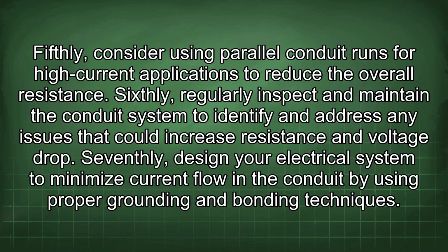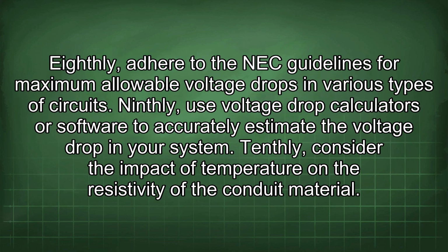drop. Seventhly, design your electrical system to minimize current flow in the conduit by using proper grounding and bonding techniques. Eighthly, adhere to the NEC guidelines for maximum allowable voltage drops in various types of circuits. Ninthly, use voltage drop calculators or software to accurately estimate the voltage drop in your system. Tenthly, consider the impact of temperature and the resistivity of the conduit material.